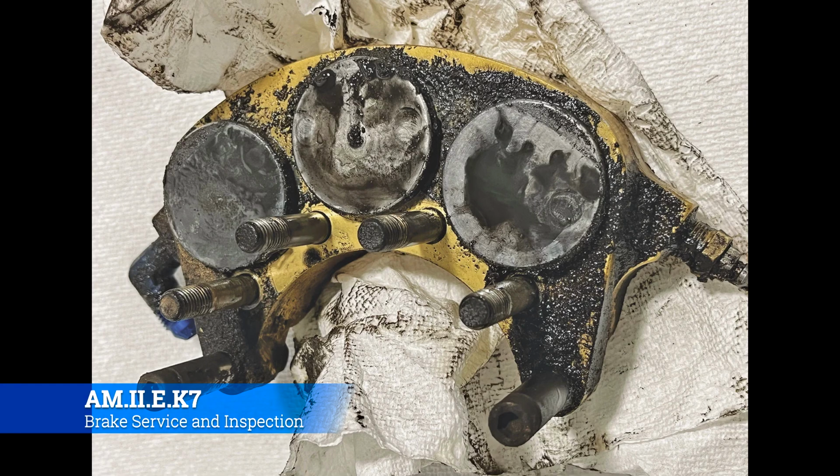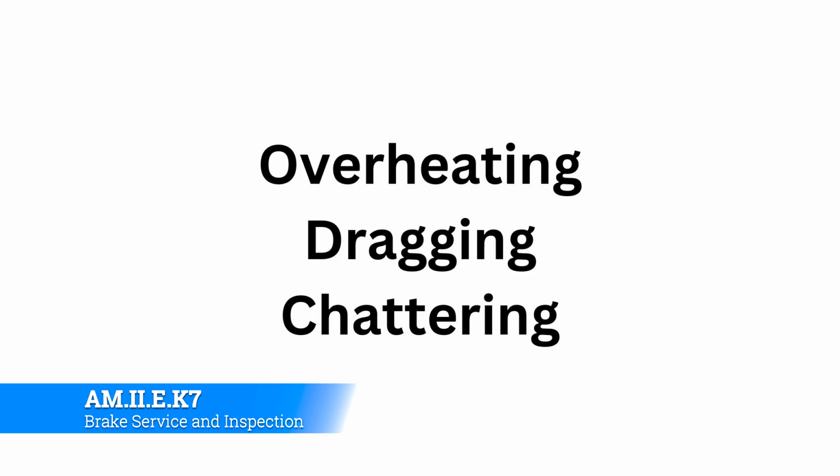All right, so let's go over a couple of common brake failures or malfunctions, and then we'll go on to anti-skid. Okay, so these are the three most common brake failures that you'll have: overheating, dragging, and chattering and/or squealing. Overheating is real simple. Somebody's just on their brakes too much.